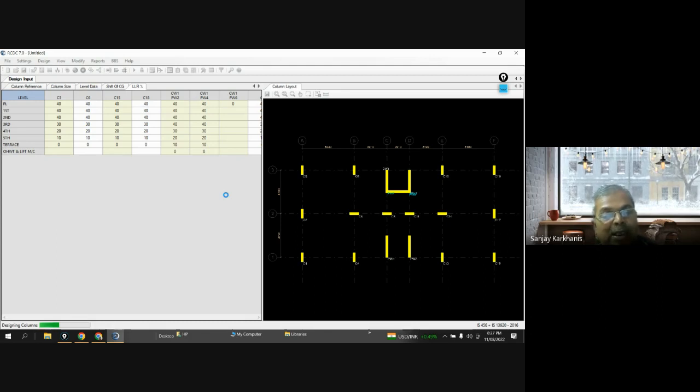That is a basic, clear thing that I am explaining. If you are defining that primary load case as a live load, then even if in ETABS you ask it to go for reduce live load, it will not reduce because the live load defined in your definition is not reduce live load.